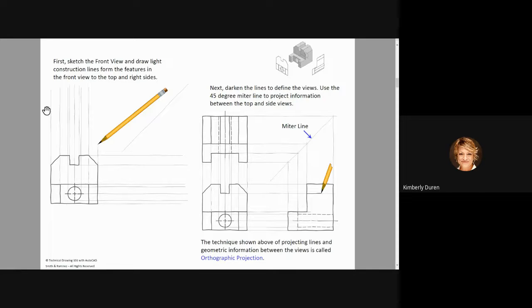So this is what I do when I draw something. I'm going to draw a box first. And then in the corner, if I'm drawing the top view and the right side view down here, in the corner of that box, I'm going to draw the end point of that wants to be in that corner, and this is 45 degrees from horizontal or from vertical, whichever one is 45 degrees. Has to be perfect 45 degrees or you'll be off.